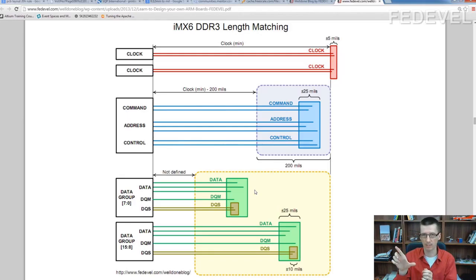The signals on the edges of the connector are longer. If you have to length match all the signals to the same length, it would be very difficult to length match the signals in the middle. You would need to make them very long. This way, if they are split into groups, you can just route and length match one small part of the layout. It's very useful.